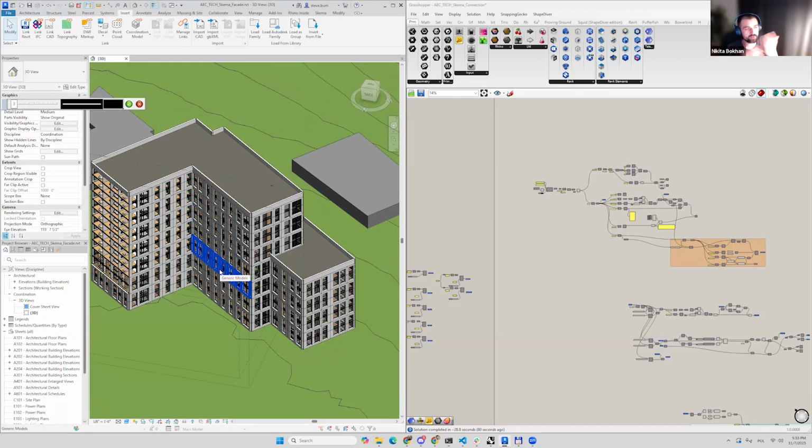So basically, for the exterior walls, we have three options to export: as curtain walls, which is completely horrible, and we have direct shapes and generic walls. For this use case, we just select generic walls. It's just a proof of the entire workflow, where the schema is a kind of mediator of the source based on which we create the BIM model.